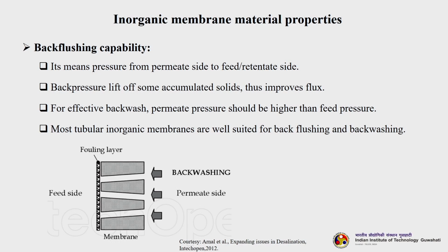Then back flushing capability, this is what I was talking about, actually washing. It means pressure from the permeate side to the feed or retentate side. You can see this is the fouling layer which is getting deposited on the surface of the membrane, these are the pores, and this is the membrane material. This is the feed side and this is the permeate side.